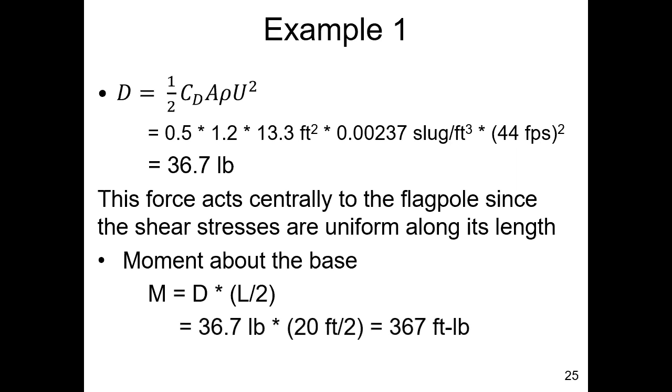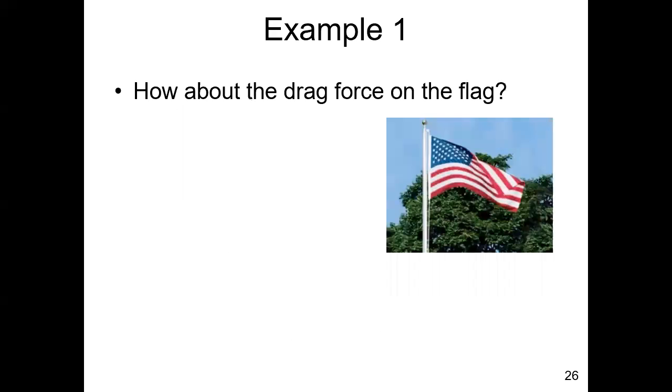So that's 36.7 pounds times 20 feet divided by 2, which is 367 foot-pounds. That's the moment about the base. But wait, what about the drag force on the flag?